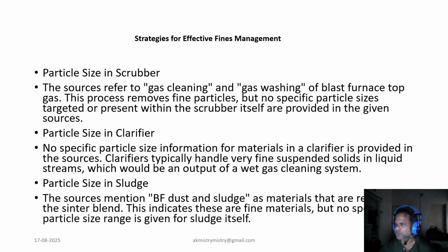For optimizing coke screening, the primary objective is to remove fine coke. Typical specifications after screening aim for a maximum of 2% smaller than 25 mm or a maximum of 3% smaller than 30 mm. While coarser coke screening can improve permeability, it also produces more nut coke or small coke, which is then added to the overburden layer.